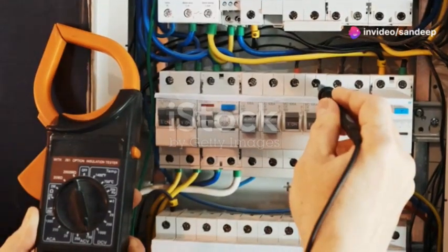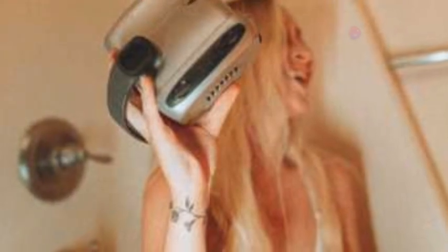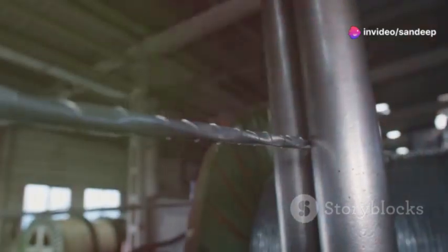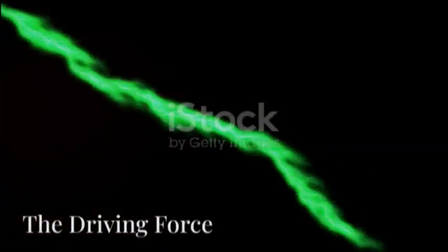We measure electric current in amperes, or amps for short, named after André-Marie Ampère. An ampere is a measure of how much charge flows past a point in a circuit every second. To give you an idea, a typical household light bulb might draw about 0.5 amps, while a hairdryer could use 10 amps or more. But just like a river needs a path to flow, electric current needs a closed loop, or circuit, to travel. If there's a break in the circuit, the current can't flow.